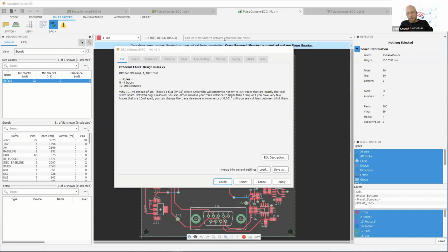So basically, I've seen this operate in two ways. It depends on the designer and the fabricator. I've seen it specified where the fabricator sets the thickness of the copper based on the desired impedance for the given trace width. So the designer will say, hey, I want this impedance for this trace width on this layer, and then the fabricator will adjust the thickness until they reach that. And the alternative is to ask the fabricator, given the stackup I have, what should my trace width be?